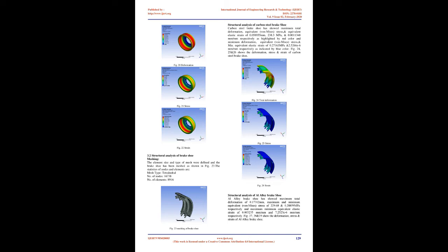Brake surface flat, mm: 187.45. Bolt circle diameter, mm: 285.75. Pilot diameter, mm: 239.776. Backplate thickness, mm: 14.22. Bolt holes, mm: 10/20.574. 2.1 Brake materials. The four materials chosen for the analyses are carbon steel, Al alloy, Al metal matrix composite (MMC), and cast iron.